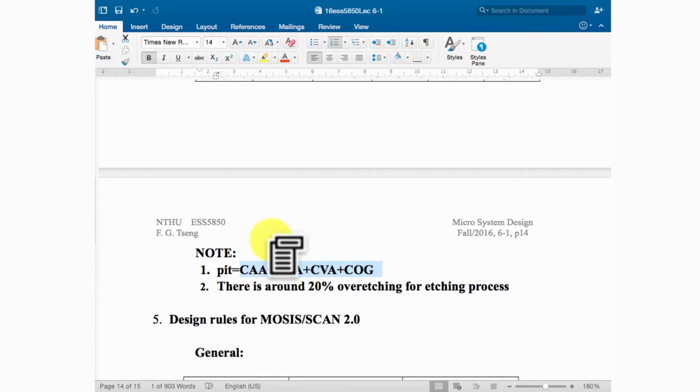to form the process. The first one, we define that area as active area. That means in that active area, we won't have any field oxide growth. Remember, we have 4 oxide layers on your surface for protection: field oxide, oxide 1, oxide 2, and overglass. So now you want to expose the silicon, you need to open up these 4 layers. First you need to define the area as an active area, so there will be no field oxide growth.